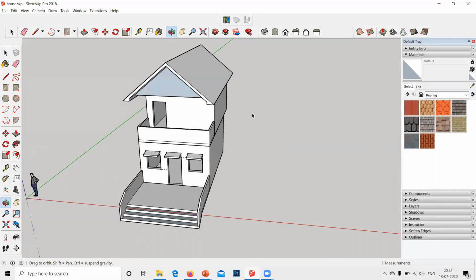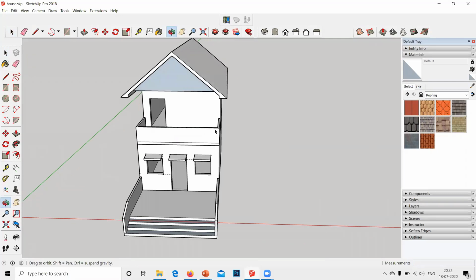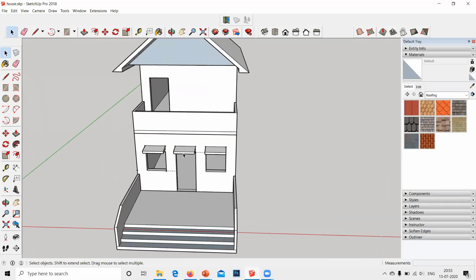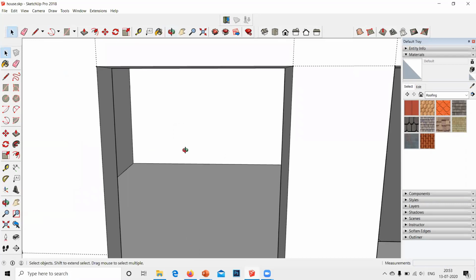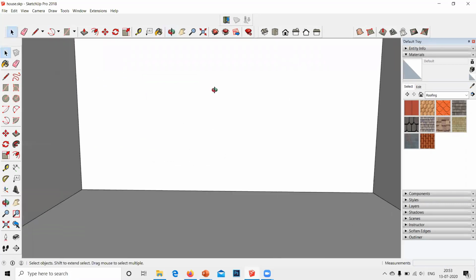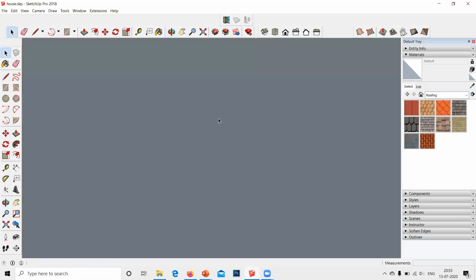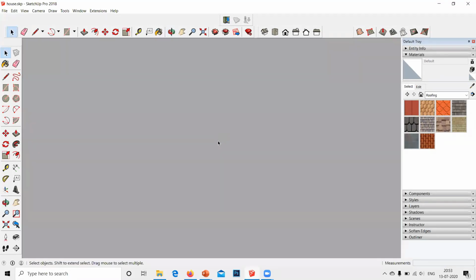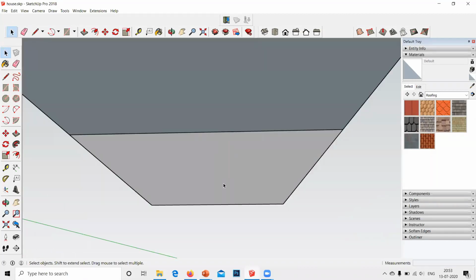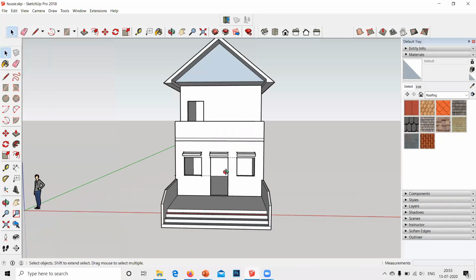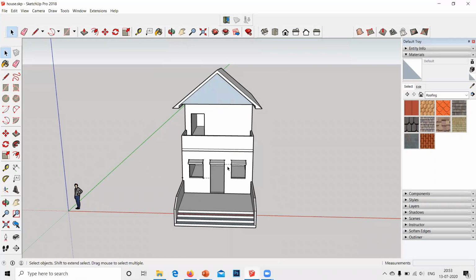As I told you, because we are going to draw an internal staircase in this small room, we are going to draw a stair texture. To draw a staircase, you might be thinking how all the texture will be reflected. All the stairs will be reflected, so it is difficult to view anything. Right click on it. Even if you pan while holding shift, all these options are coming there. So it is very difficult to actually go inside a stair once the model is complete.